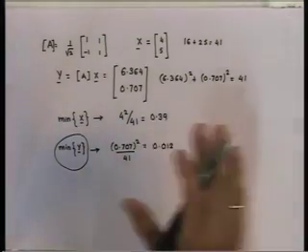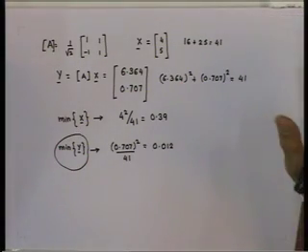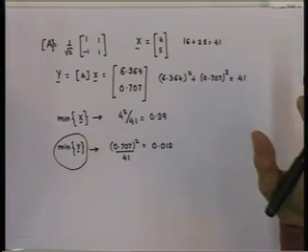Now, in both the examples, we could reduce the number of samples we needed to code, because most of the information or energy contained in a pair of values was put into one element of each pair. Because the other element of the pair contained very little information, we could discard it without a significant impact on the fidelity of the reconstructed sequence. Now, in both these examples, we formed a vector of length 2.